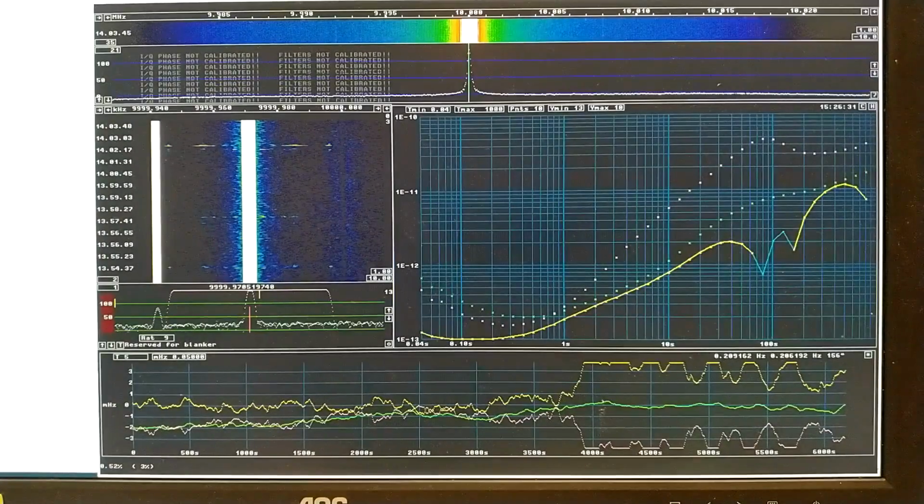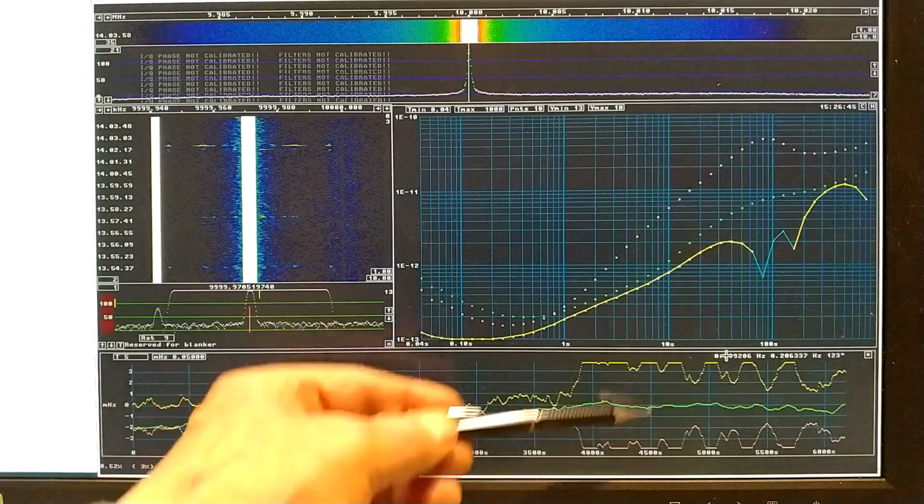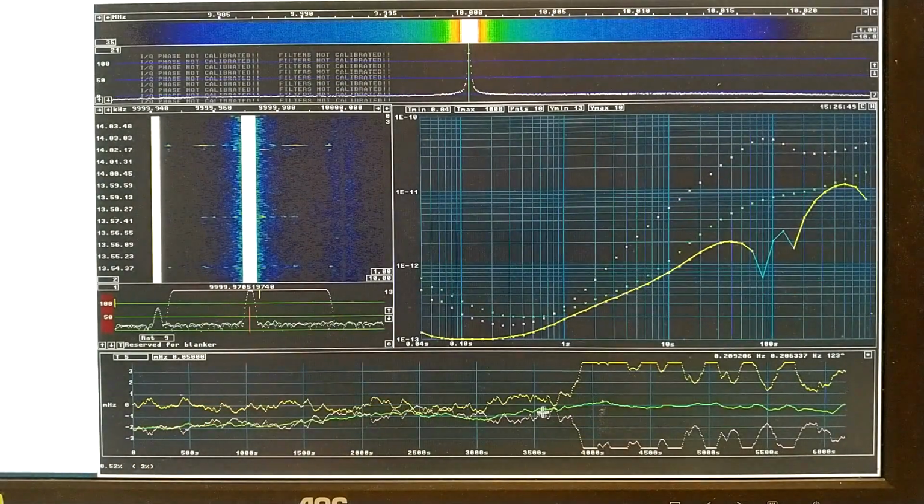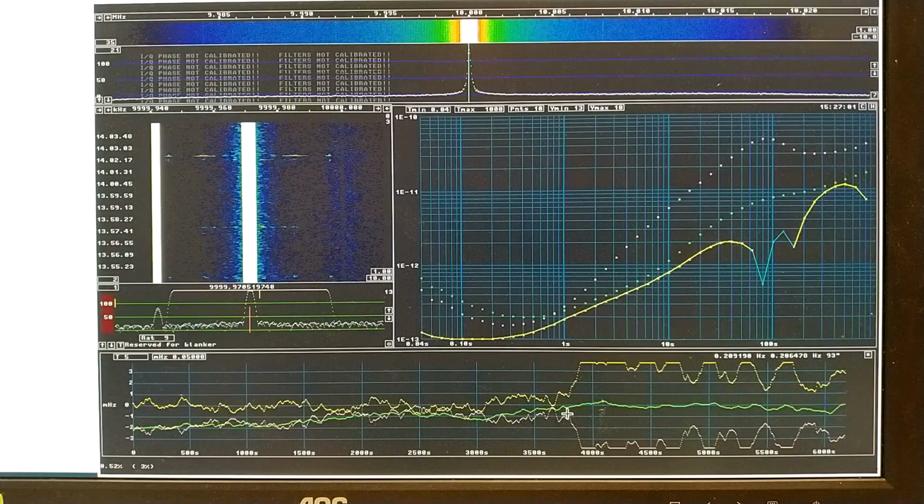And then I have a third instance of Linrad running. Here I'm looking at Allan deviation or Hadamard deviation. This is the Hadamard. Now you can see something happened here. That is that the PLL stopped working. I got outside the capture range, or what it's called, lock range. So channel 2 is now running some 4 millihertz away from channel 1.